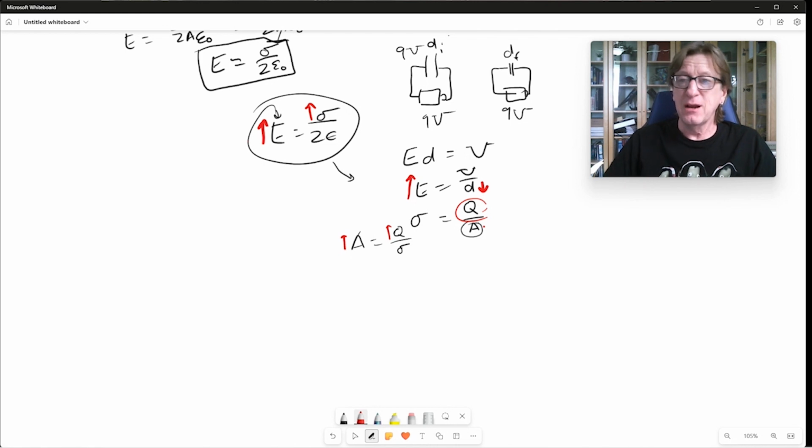But air is a wonderful insulator. It works extremely well. And so you're not getting charges. Let's use a different color. You're not getting charges jumping across like that. That's why you don't get sparks in between your capacitor. It just stays on the plates. However, if the electric field gets high enough, then the air will actually ionize. It'll break down. And that's the point at which it does because of its dielectric constant. But the air will eventually break down. It'll ionize. And so now it will conduct electricity and zap the way that goes.